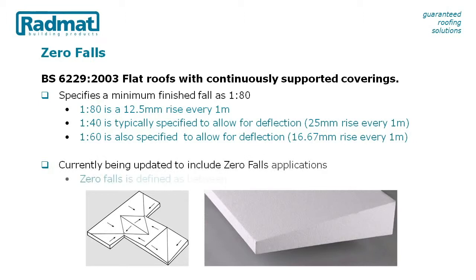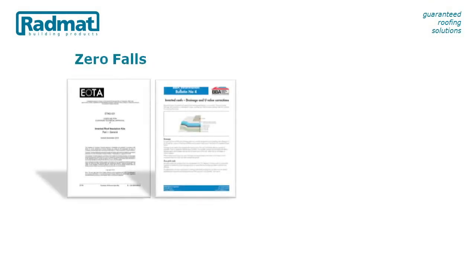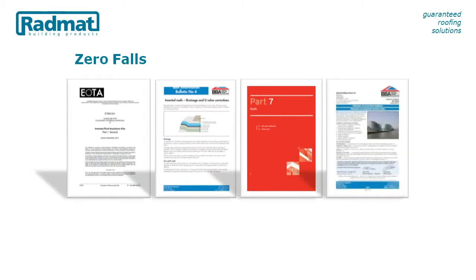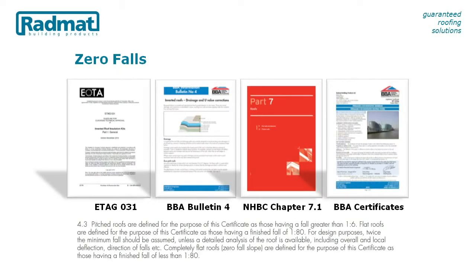But 2003 was a long time ago, and in 2016 BS 6229 will be updated to include zero falls applications as defined by the British Board of Agrément in Building Bulletin 4. Building Bulletin 4 is basically a précis of the requirements of ETAG 031, the European standard we talked about earlier when discussing insulation. So not only has Europe recognized that zero falls construction is acceptable, the BBA have produced a simple guidance and will certify products for zero falls application.